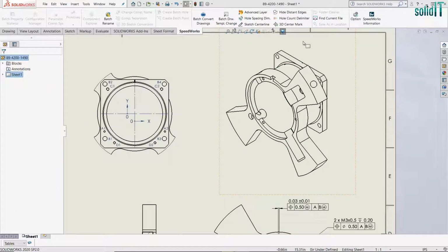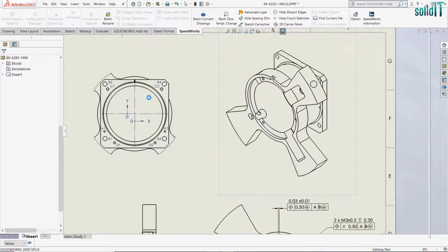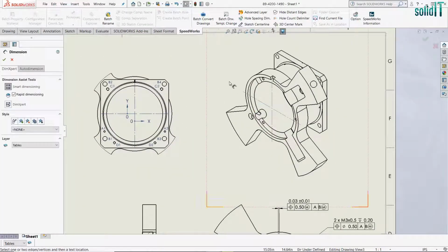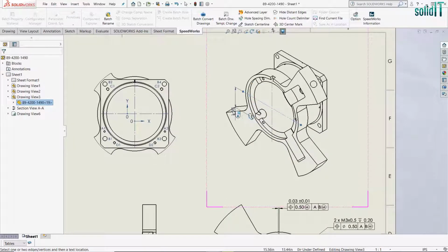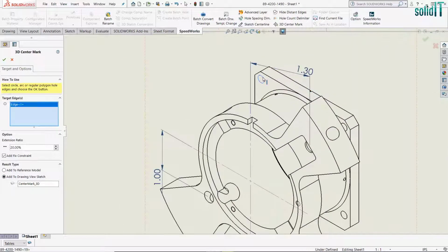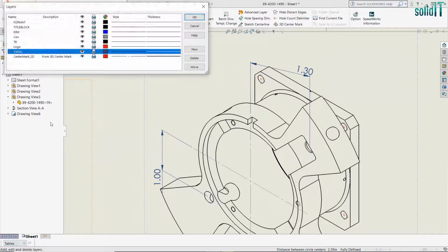It is very challenging to create a centerline in 3D drawing views like isometric view, ISO view. However, through the 3D center mark function, a center mark can be automatically created at the desired location, allowing you to create a view of the desired design. In addition, it is possible to input actual dimensions based on the created center marks. This makes it easy to create highly useful center lines.